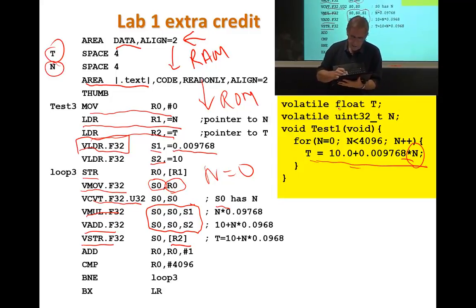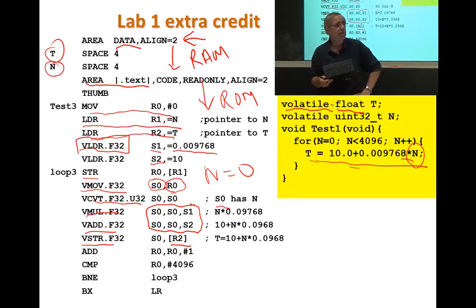In C, what does float do? Creates a floating point variable, remember? What does volatile do? No, volatile means remove all compiler optimizations. In this particular program, if I store into t, and I don't ever read it, it's going to optimize it and take it out.